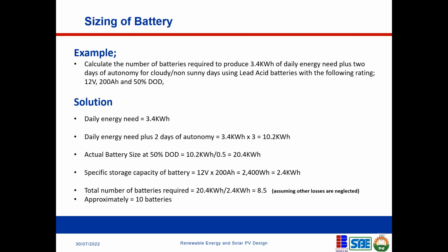No, sir. You have 10 batteries. 2 of them form 24 volts. Then among the 5 pairs, each pair is 24 volts. When the 5 pairs are connected in parallel, it forms 24 volts as a parallel connection. I don't know whether I'm right. Yeah, you are right. Then okay, still 10 batteries, but in 5 pairs. Yes, in 5 pairs. That's correct.